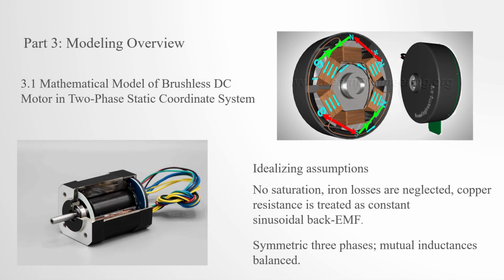In this part, I built a mathematical model for surface-mounted BLDC under some idealizing assumptions. We assumed sinusoidal back EMF and a symmetric three-phase stator, identical phase resistance and balanced self-inductance. Magnetic saturation and higher-order harmonics are neglected.